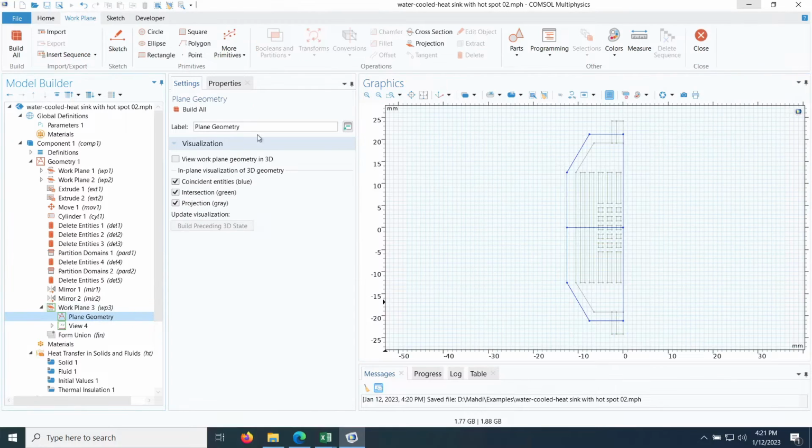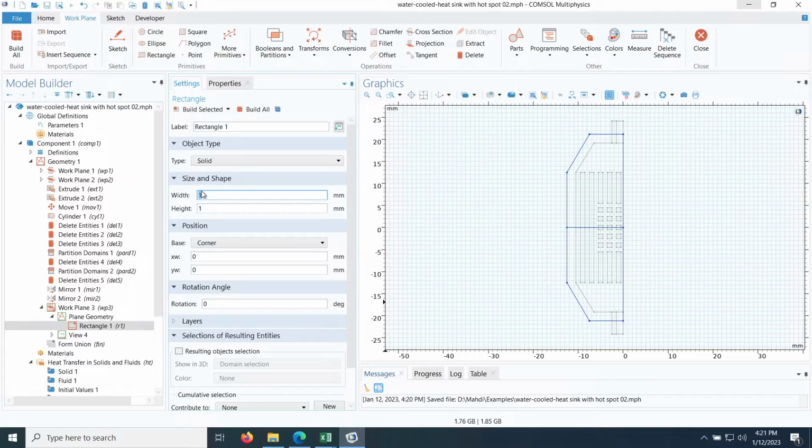And right here, I want to create a rectangle, 5 millimeters in the X direction and 10 in the Y direction. The corner is going to be at -12.5. Actually, this is going to be 12.5 in the X and 25 in the Y, because that's the entire chip. -12.5, put 2 dots there, and -12.5. So that would be the chip itself, but now I have to create a hotspot in the middle.